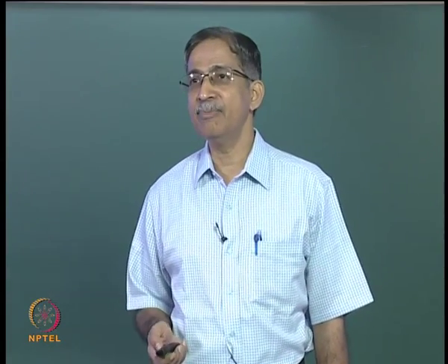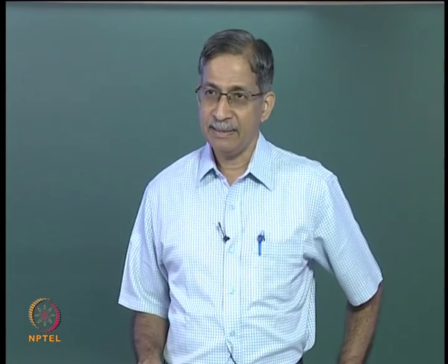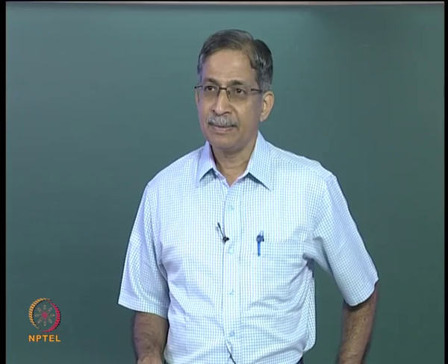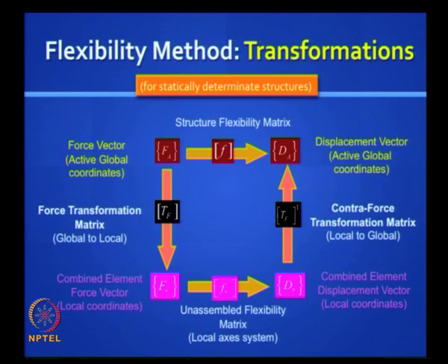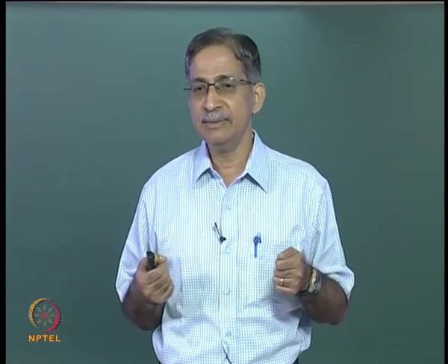And there is the contragradient principle which links D star to DA, that is the TF transpose matrix. What is the use of this matrix? Can you tell me? Where does it help us? In trusses, how did it help us? Lack of fit. If you have some initial displacements in a statically determinate rigid structure, a truss, you can find out the joint displacements caused by these movements.